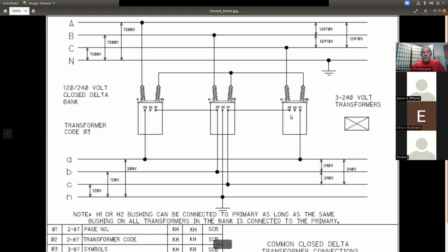Both of these transformers are going to be a power transformer or high leg. So I'll start in the center. Right, left and right. Okay. So if there's just two transformers, the left one's always going to be lighting, but if there's three, the middle one's always going to be lighting. Correct. Gotcha. Good deduction there.